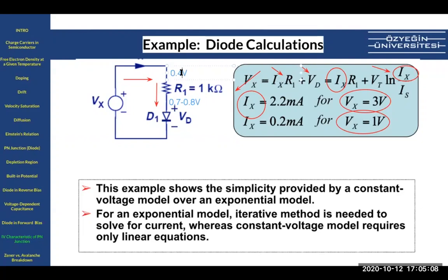If this is 0.9, for instance, or if this is 0.8, now we'll start to have current flowing, because this 0.8 volt will be enough to force the diode junction to get smaller and let the diffusion current flow. And now R1 will be happy because it will have some current on it, so it will warm up. There will be some power dissipated on it, right? That's how we use these diodes as switches.